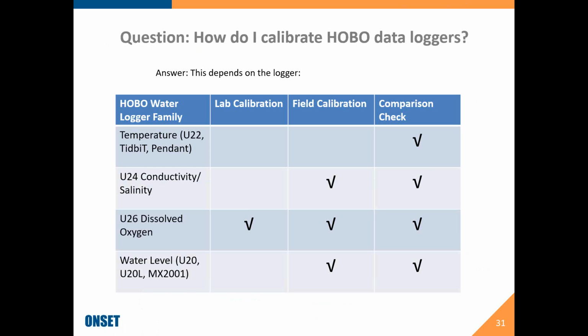If there are some outliers, don't use those outlying data loggers for the deployment. It's a good, simple way to check the calibration is still accurate. The temperature loggers do remain stable for many years, but it's always good to check them before a deployment.